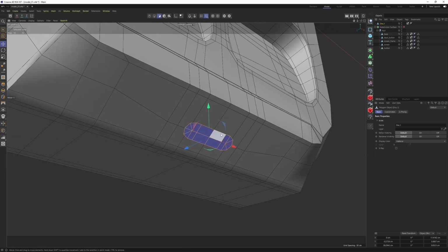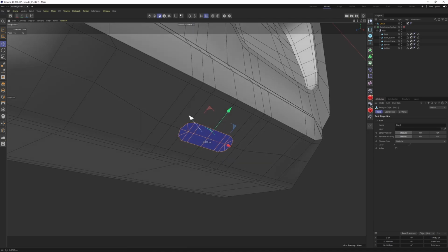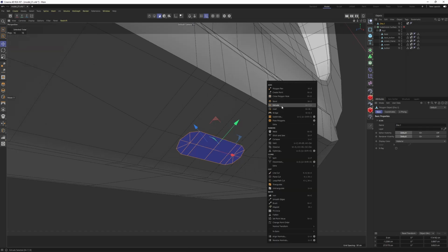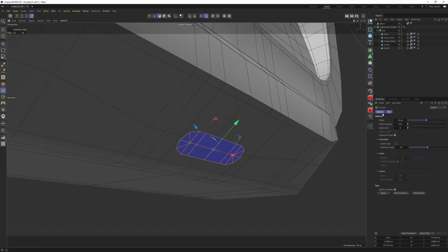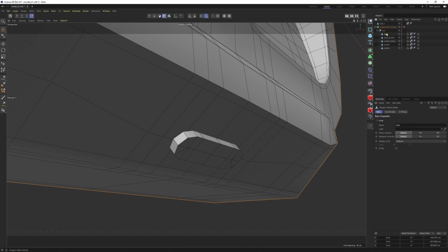I'm gonna select this one again and select normal axis, pull them just a bit. While all the polygons are selected, select extrude tool, enable create caps. I did this because I will use a bool. Select the base, hold down Alt, bool, and put the disk under that.